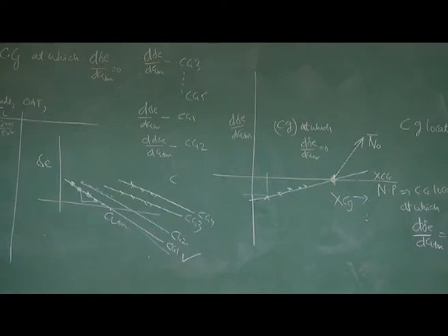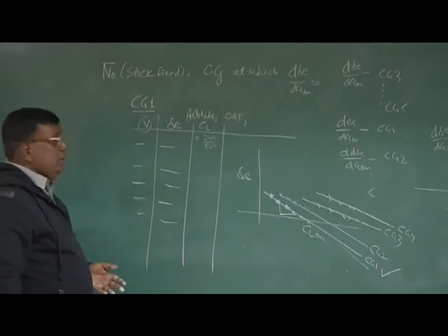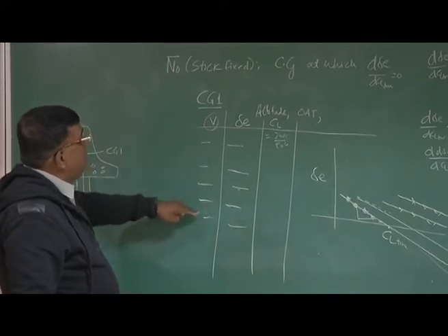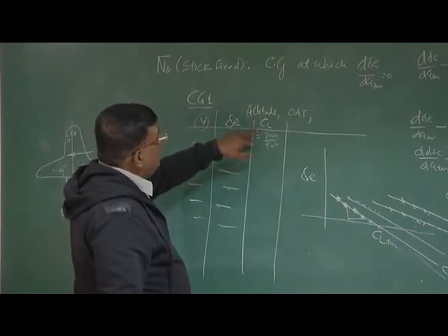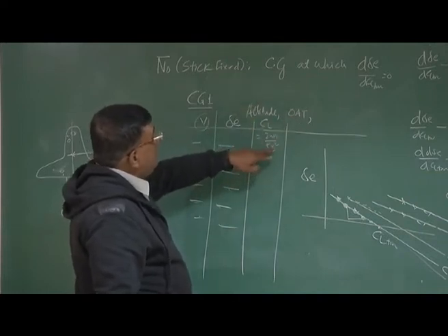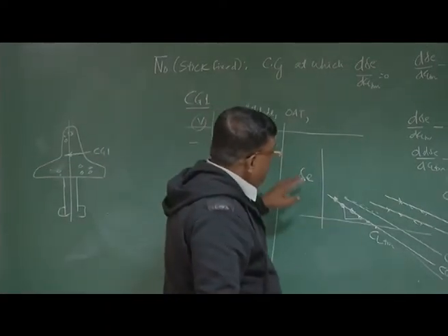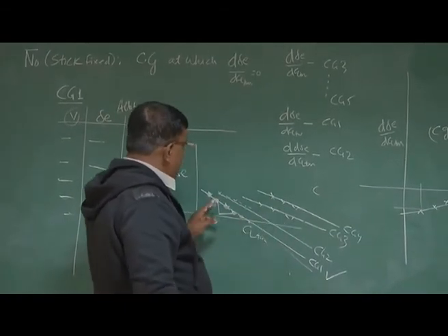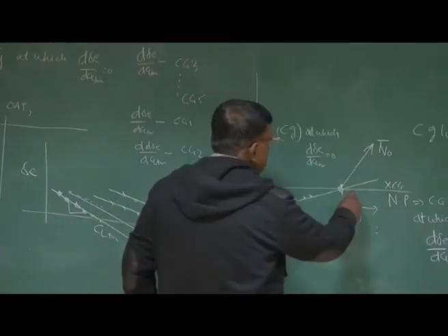You have to go to an altitude, you measure the altitude and outside air temperature. These are important to get the density of air. Then you cruise at different trim speed, V1, V2, V3, V4, V5, measure the elevator deflection required for trimming it, convert V into CL, because for CL you need rho, so this outside air temperature and altitude will help. Also V, so indicated airspeed. So all this after you have done, plot delta E versus CL trim. It will come like this for different CG location, take their slope, cross plot d delta E by dCL trim versus xCG. Okay?